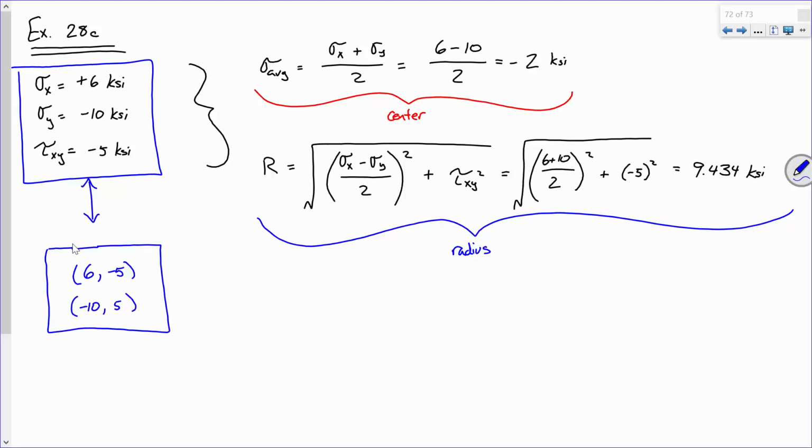Those are just the values that we got putting our x and y axes on our beam or column or shaft or pressure vessel or what have you. We just put those coordinate axes where they made sense. The values that really matter are principal stresses and maximum shears. If we turn that principal orientation, it's funny how we get back to right where we started.